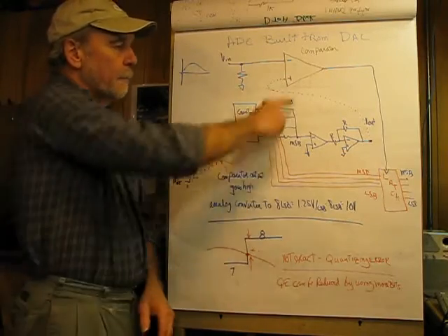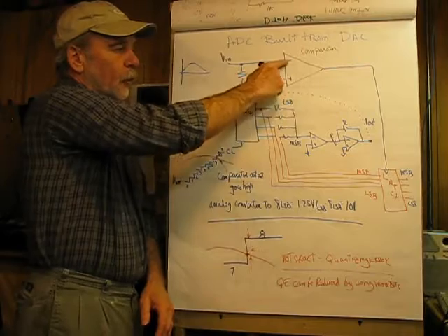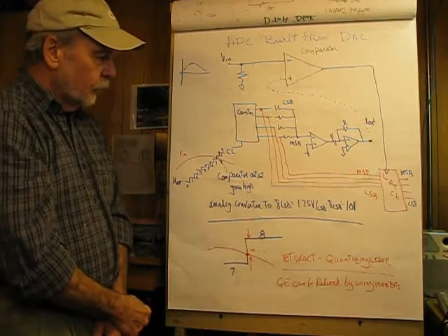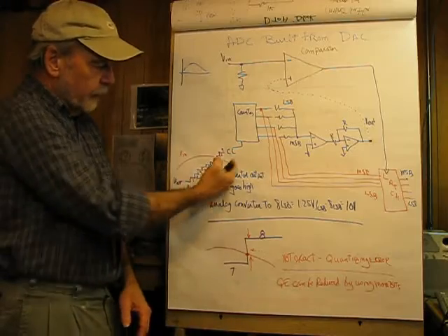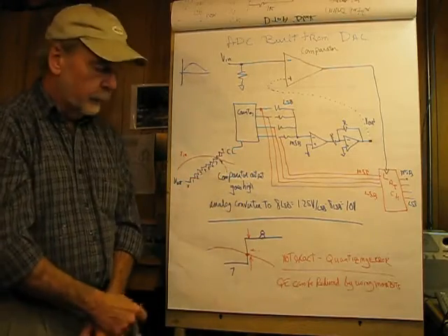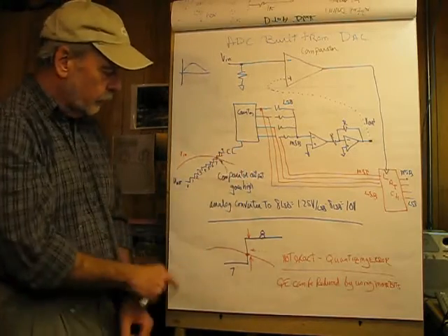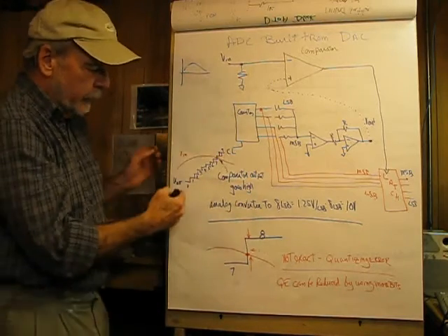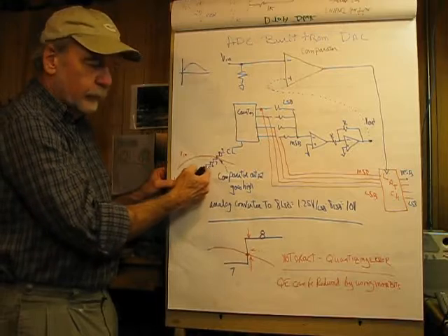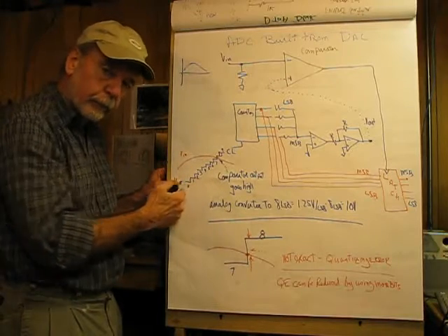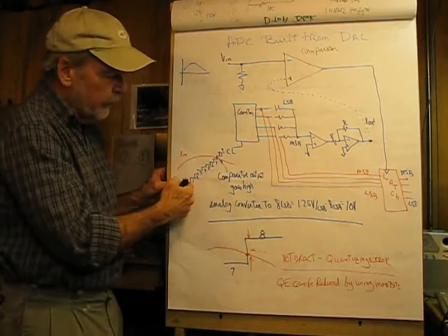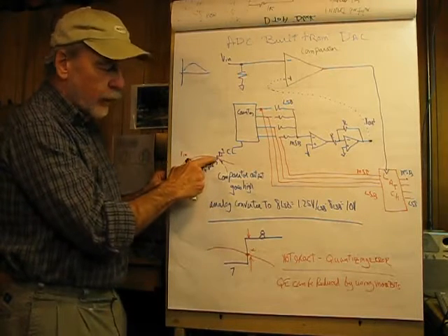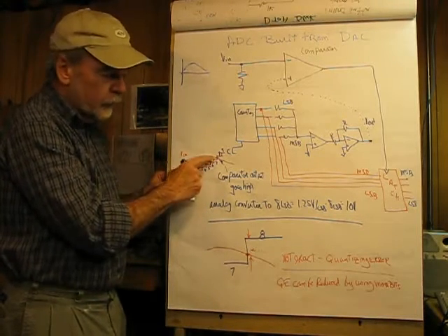So what we remember is that if the non-inverting input is more positive than the inverting input, the output goes high. So we're going to take our stair step that we generated on the other page that I've kind of smashed in here, and this is going to be our input voltage appearing here. Then we simply up count with the 4-bit counter, going through our binary weighted network here until we cross over the input voltage.